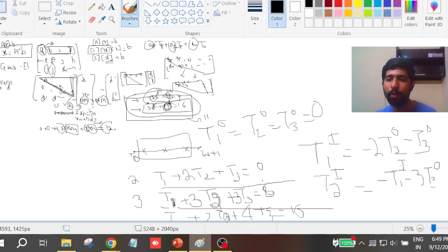So whatever we know, basically we will take at the current iteration only. Whatever we don't know, we will take as previous iteration. This will just speed up the process. In Jacobi method, we put everything in terms of iteration 0 only for T1, and for T2 as well; that is the main difference there. Then similarly we calculate T3 using the third equation, but here we put T2 and T1 both at first iteration because we know both the values.